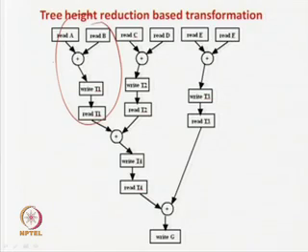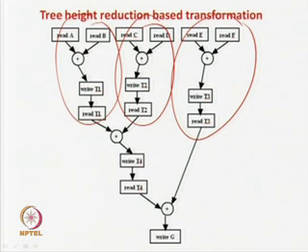Now in this case, see, we are doing A plus B in one go, C plus D in one go, and E plus F in one go. Then we are adding the values of T1 plus T2, these temporary variables, in another step, and in the third step we are adding the value in this one. So, how many adders have we put? 1, 2, 3, 4 and 5.